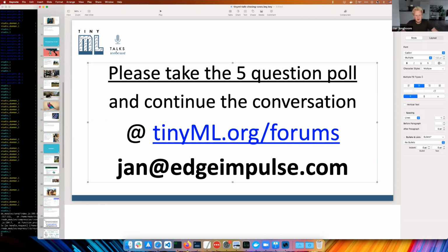So for us, TensorFlow is not just a place where we train some neural networks. We use some other stuff as well, by the way, to do non-neural networks, but it's the cool part where, we want to deploy something in Cortex-A. Okay, there's XNNPACK, right? That has really fast code with SIMD instructions on Cortex-A. We want to do something in Cortex-M or ARC DSPs. There's actually TensorFlow Lite for Microcontrollers. There's something new and interesting, like quantization of our training. It's always in TensorFlow first, and that has been really cool.